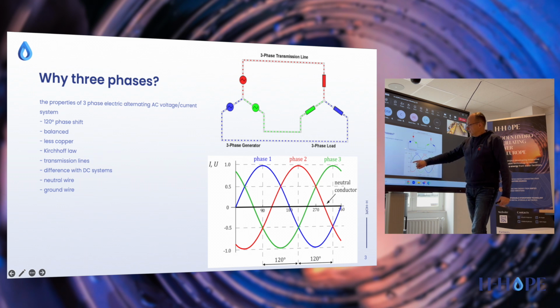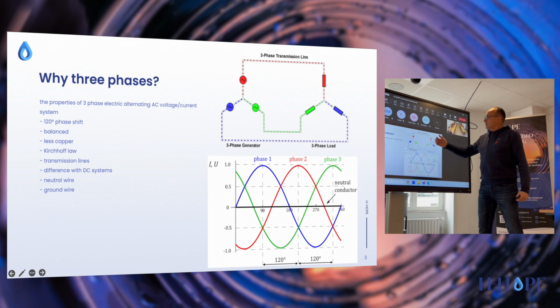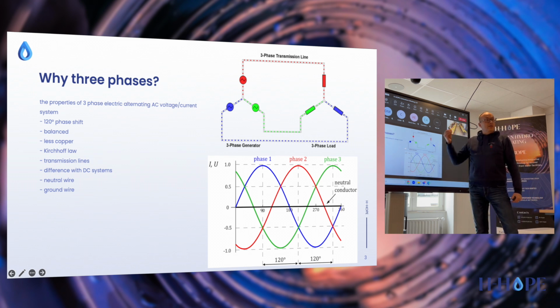And at this particular point, exactly at the start, the blue one is 0, and the green and the red are approximately the same, just opposite. So that actually means that the net flow is always 0. The sum of these three phases always equals 0, and that's also reflected here. That's why we can connect them together, actually.